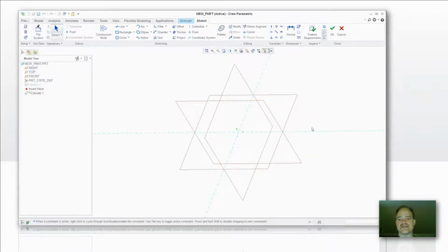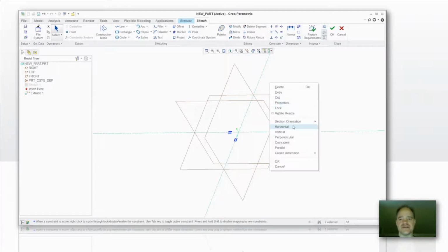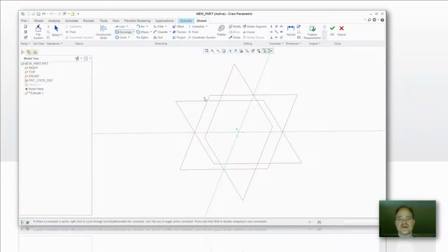And the other thing is, if you're used to having center lines, put those center lines in your template also. But in this case, I'm just going to create a quick corner rectangle. I'm going to use those center lines. The value of the center lines is now I snap to symmetry during the process.